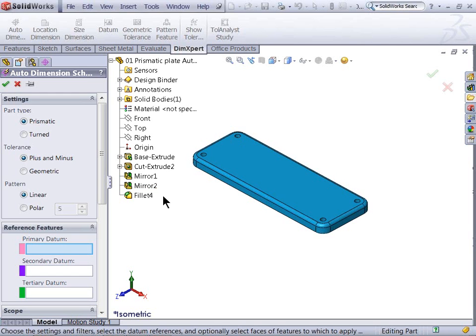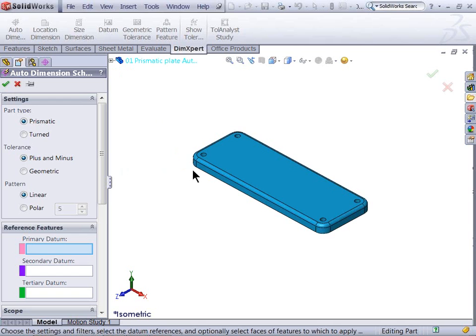So in Essentials, we hammer very much planning out your datum structure and modeling from it to get usable dimensions in your drawing. Well, here's kind of the next way to handle this, and that is to use DimXpert to set up your datums and get the dimensions for your drawing. And when we get over there, I'll share that. But that's just to give you an insight into what DimXpert is doing. It's ignoring all the features in the tree and just treating it as geometry.